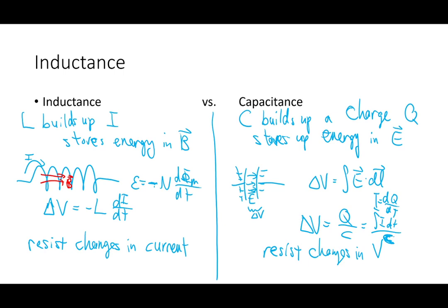They both store energy, yes, but more often we think of capacitor as a storage of energy because we're more used to dealing with having a certain potential or certain voltage, rather than having a source with a certain current. So in most cases, the application of inductors is not so much for energy storage, but rather it's really based on this particular form, which is different from the one for capacitor, and giving us certain various filtering kind of aspects. So from that, you can also see a very parallel process of developing how much inductance there is for a given shape, size of coil. Very similar to the capacitance case.